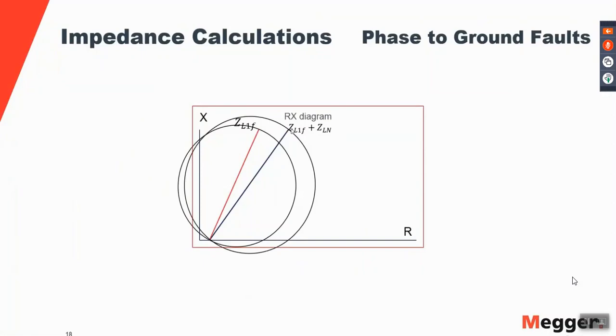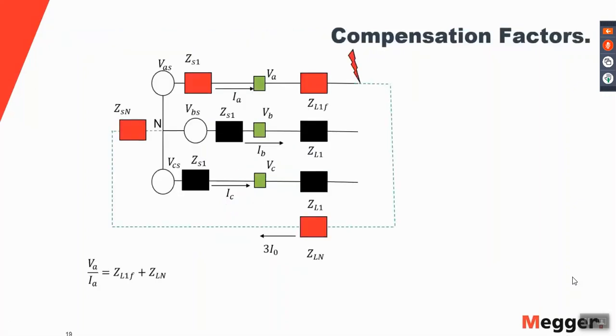We're going to see a higher impedance, which means that for this particular case, if there is no compensation applied, even though the fault is here and it's clearly on the limit, then the system, or the protection, will not operate. So we have to find a way to counter the effect of that for the phase to ground faults.